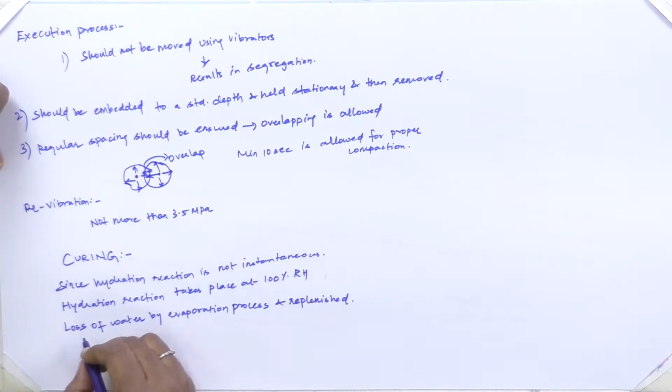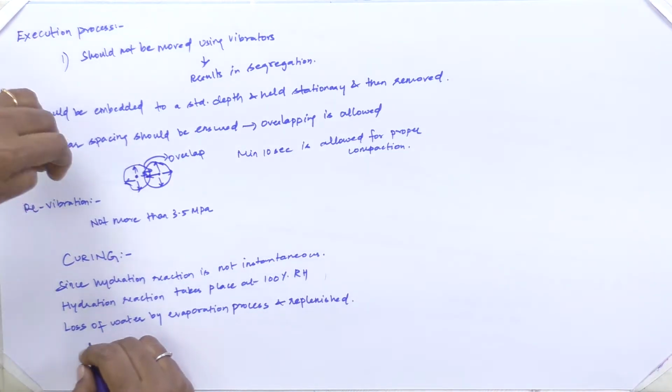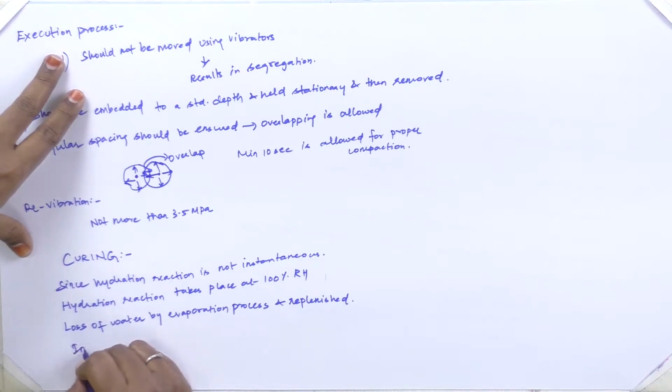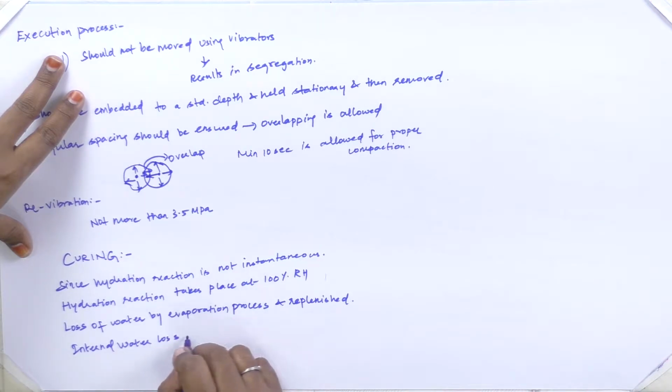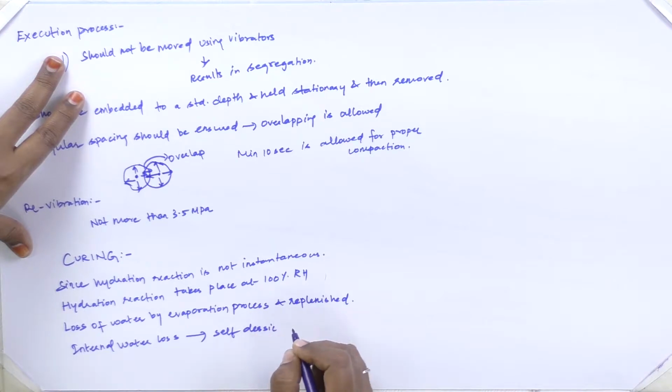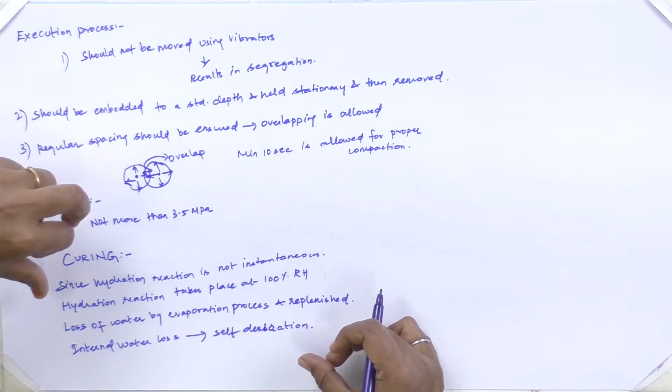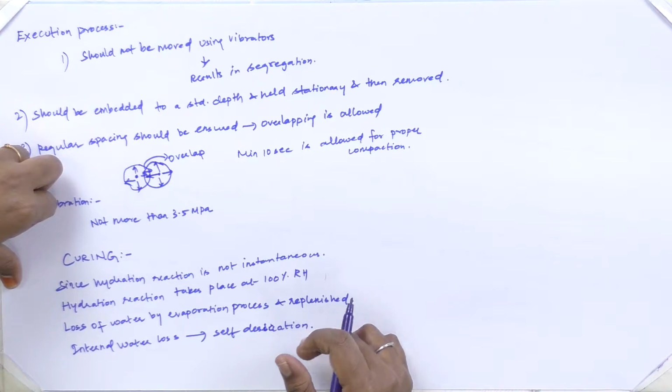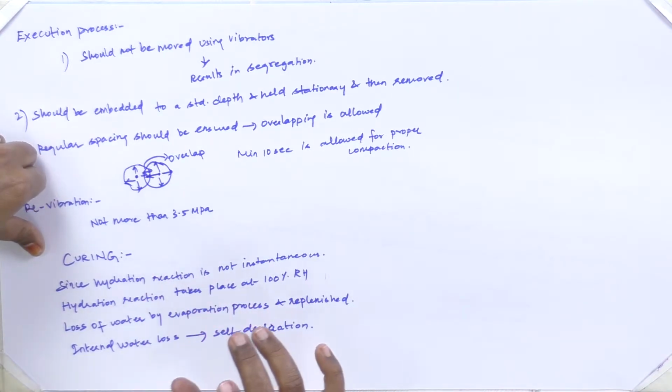And internal water loss can also occur due to self-desiccation. So in order to prevent all this, we go in for curing.